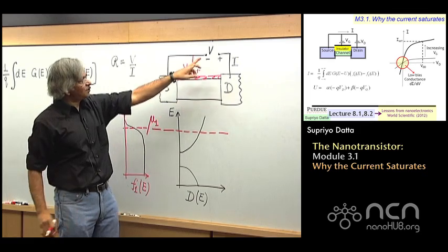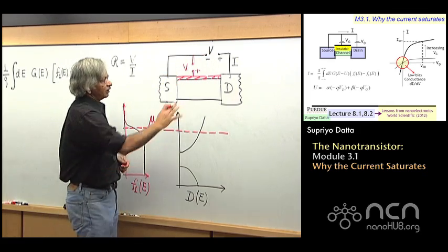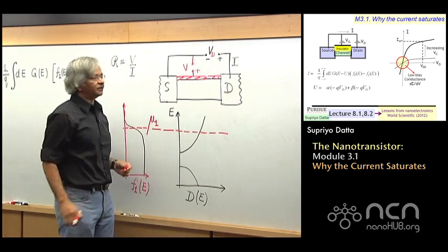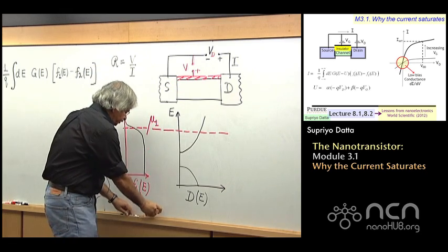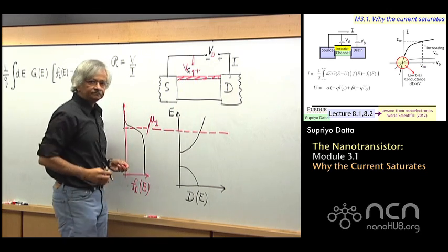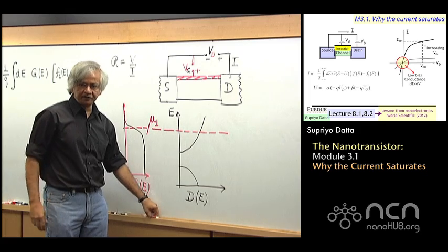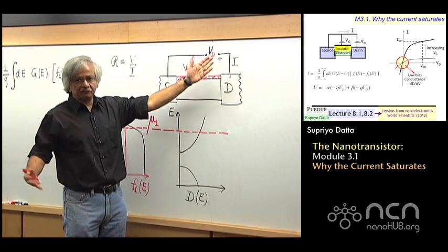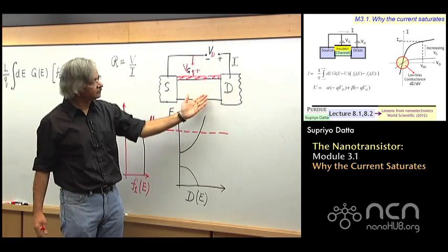And to distinguish between the two voltages, now that we have two of them, one of them is called the drain voltage, as you might expect, because that's the voltage that's applied to the drain. And the other is called the gate voltage, because this third terminal is called the gate. So those are the two voltages, and their purpose is very different. The drain voltage, like the voltage we talked about before, causes current to flow in this channel.